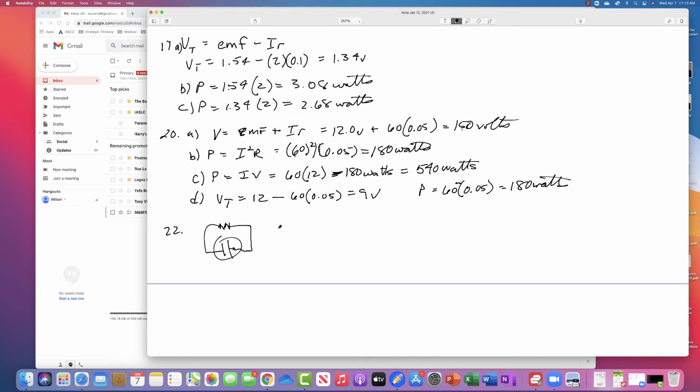using the nickel-cad batteries, you have a current that's equal to E over R plus r. So that's going to be 1.25 for the nickel-cadmium and 3.2 plus 0.04 for the internal resistance.